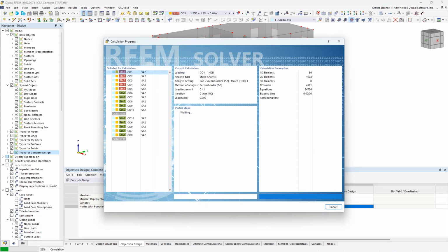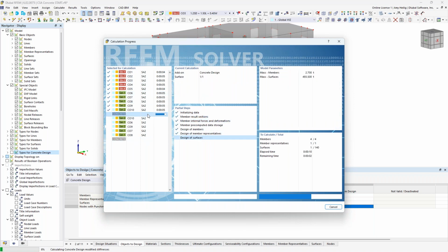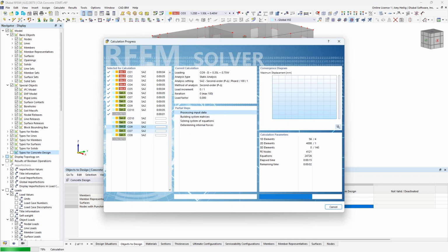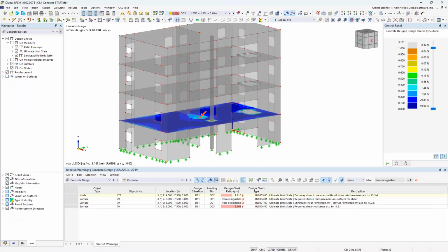And you can see that the program will now cycle through all of my load combinations here for the analysis portion, taking into account topics like the I-crack factor. You'll also see here that we rerun the serviceability load combinations, and this all just relates to that effective moment of inertia that we need to recalculate to determine the deflection checks within the concrete design specifically. And finally, we carry out all of the additional ULS and SLS requirements to give us the design check ratios for all of these elements we have considered.